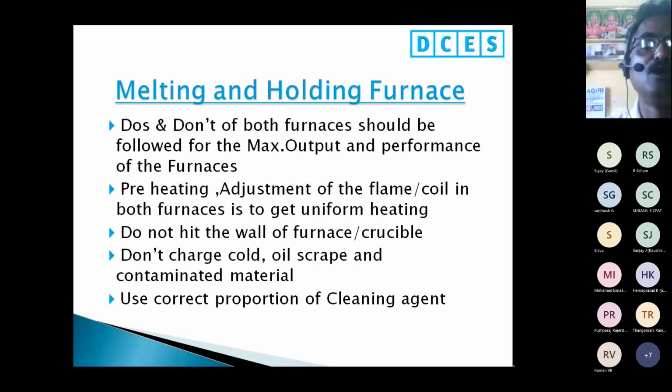Do not hit the wall, as I said previously, on the furnace and crucible. And don't charge cold material. Sometimes the operator wants to supply material to the line and immediately charges cold material. What will happen? It will burst, or sometimes it will take more heat. It should be preheated beforehand. And oily scrap and contaminated metal should not be charged in the melting furnace or holding furnace. It should be treated separately.